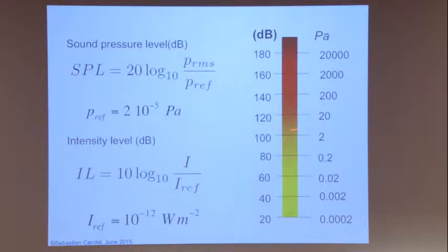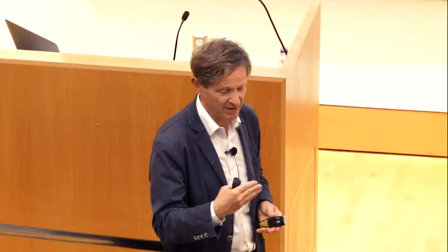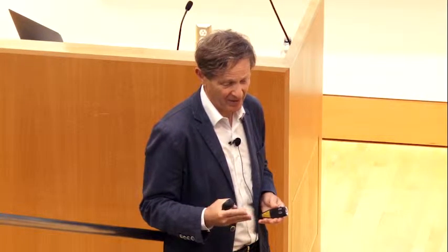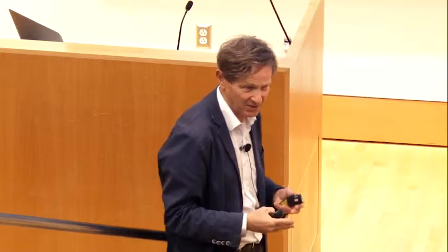100 decibels is 2. 120 is 20 pascals. 140, 200. 160, 2,000. 180, 20,000. And we've been able, in a box, to reach 210 decibels. We had acoustic waves produced in a box at a level as high as 20 bars peak to peak. So 20 bars at a kilohertz, not at zero frequency, at a kilohertz. So that's perhaps a world record. I don't know. Not quite, because the rockets produce even higher levels.